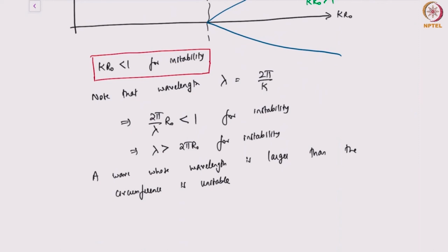So this is a long wavelength instability. Any wave larger than this is unstable, but if the wave is actually smaller than this wavelength, then surface tension will not prevent those waves from growing, because surface tension is most effective at small scales.